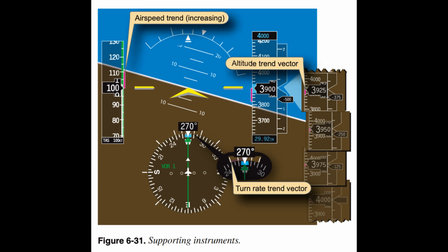A rule of thumb for correcting altitude deviations is to establish a change rate of twice the altitude deviation, not to exceed 500 fpm. For example, if the aircraft is off altitude by 40 feet, 2 times 40 is equal to 80 feet, so a descent of approximately 100 fpm allows the aircraft to return to the desired altitude in a controlled, timely fashion.